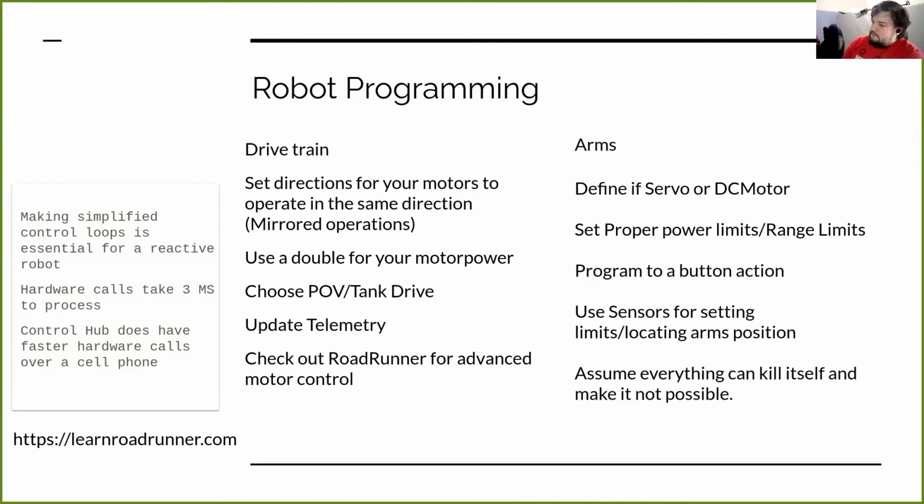And every sensor, going back to programming it, make sure that every sensor is properly named, that it's clear, not color sensor 1 and color sensor 2. Because now you have to have a reference sheet that explains what is color sensor 1, what is color sensor 2. Do arm color sensor. Or if we have color sensors on the left side and the right side of the bot: left chassis color sensor, right chassis color sensor.